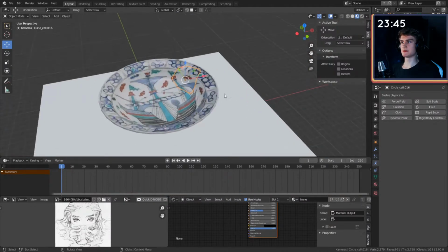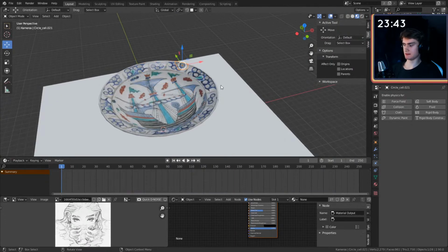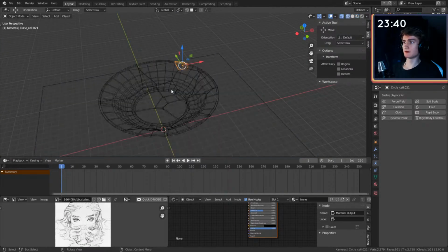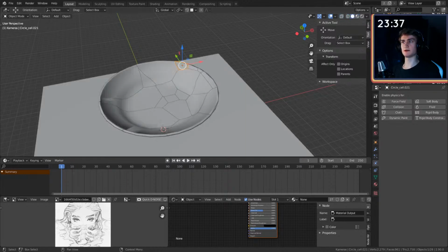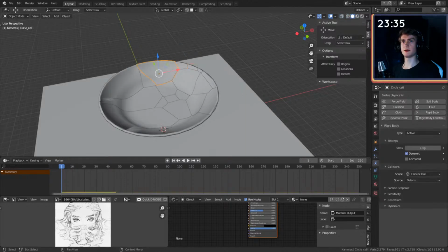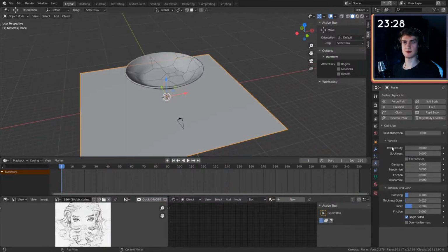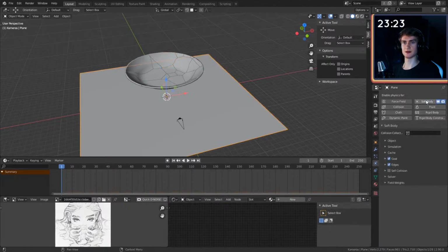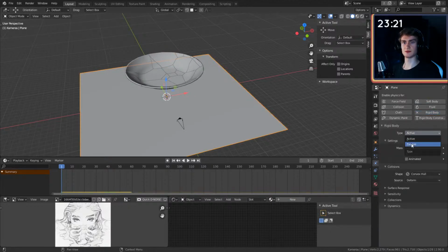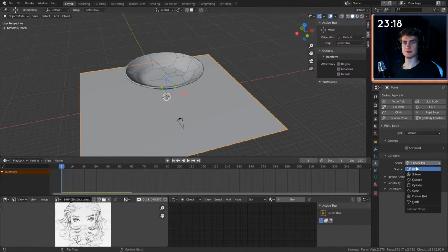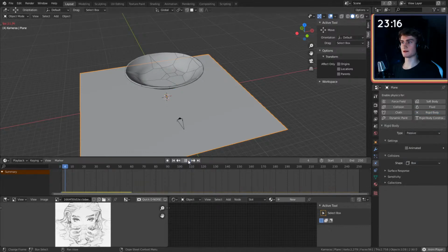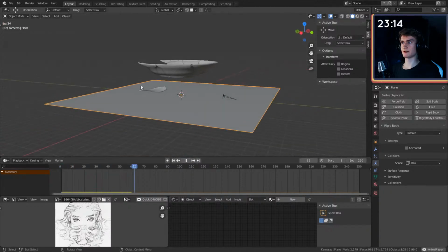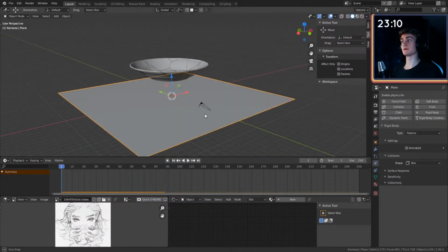So we have to do something else. Let's go to wireframe, or actually let's go to solid. I'm hoping the standard settings are pretty good. The plane is not a collision object. Why is it not? Oh, I think you have to go in here and not use collision, but rigid body, and then put that to passive. Shape, box. Let's see how that looks. And there you go. It's lying on the ground, which is what I wanted.